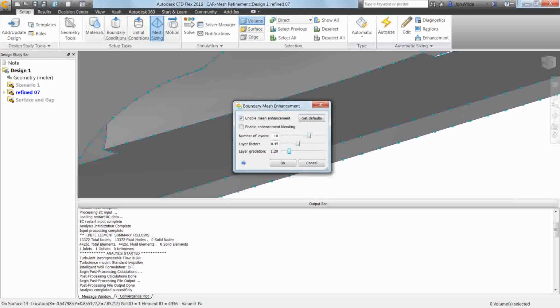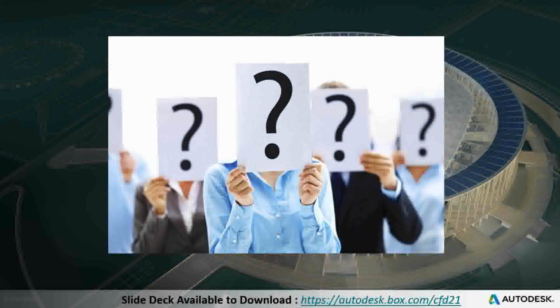Okay, I can see one other question that I guess we haven't answered really. Do we have any specific advice for meshing in a compressible flow analysis? Only really what we've already said, I guess. With compressible models, you might have regions where the density and temperature change really quickly, or you might have shock waves. And again, those are the regions where you're going to want the most mesh. I'm running one right now, and CFD's adapting really nicely, and it's capturing these rapid density changes really well automatically. So yeah, just start with a good mesh. Be mindful of where those big changes are going to happen, and I guess that would be my answer.